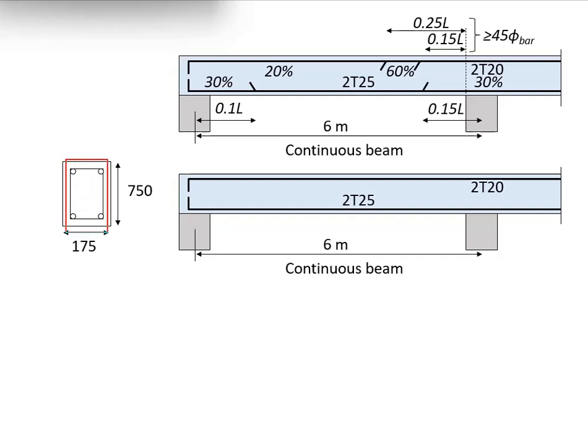These 4 units of reinforcement bar here are required for the tying of the shear link, one at each corner of the link. With this setting of the minimum amount of reinforcement bar, you cannot stop this 2T20 at any area here, as this region will still need reinforcement.